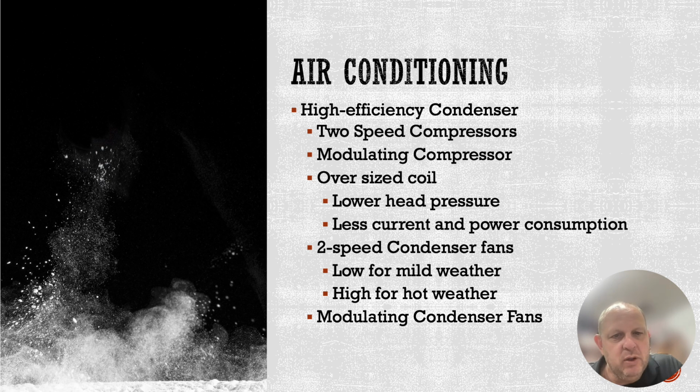We've oversized the coils on the outdoor unit. And what that does is it drops the pressure on them. So we're consuming less electrical energy as the coils are oversized.